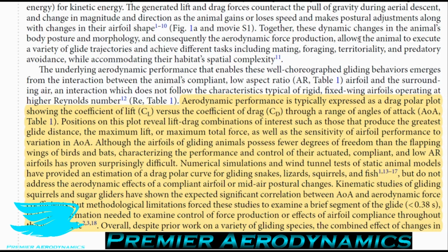So first of all, bats and birds and most insects, they flap their wings, and this creates a transient lift production. And this is often characterized by a lot of different vortices coming off from different areas. We've covered this in other podcasts, but just briefly, these vortices produce regions of low pressure and help keep the flow attached over the airfoil so you can produce more lift, and even potentially increase the camber and thickness of the wings. So they act like thicker wings and more cambered wings, so you get an increase in lift that way as well.